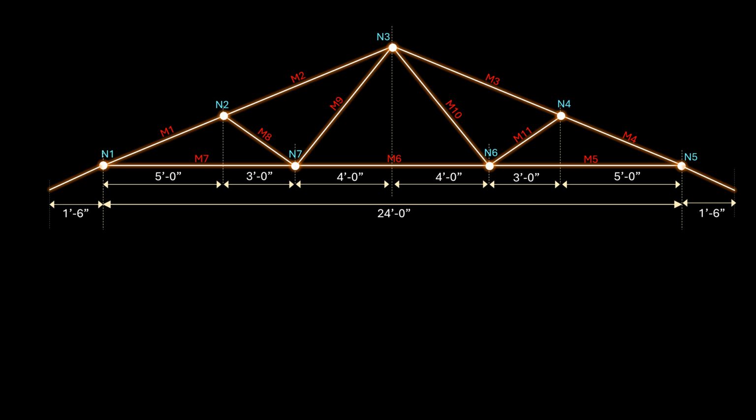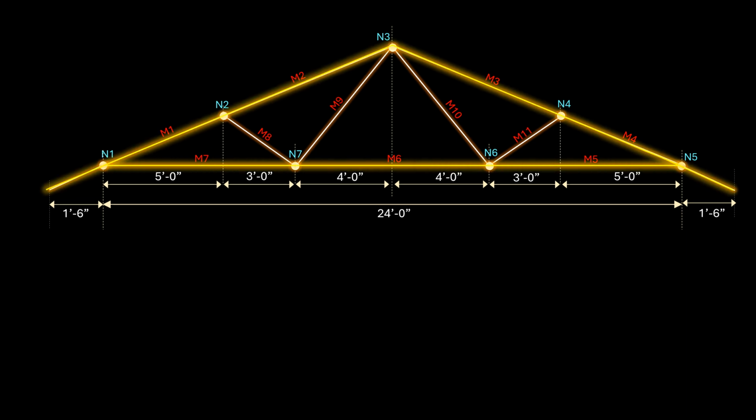As we have noted, the trusses are spaced at 2 feet on center and are supporting uniform load. Members supporting uniform loads along their length will be subjected to both bending and shear forces. This means that the top chord and bottom chord members will also be subject to bending and shear and must be designed against these loads. As we noted at the beginning, the scope of this example only includes axial loads. Therefore, we will strictly focus on the determination of axial loads at this time.